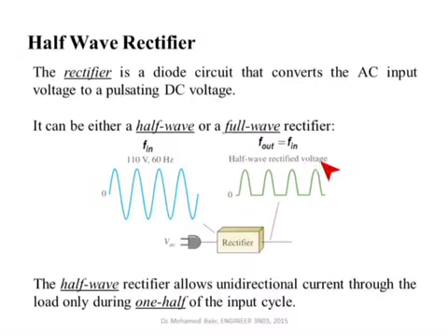So only positive voltage is allowed to go through. We call this a DC voltage because if you connect a resistor across this voltage, the current will flow only in one direction because the voltage is positive. But of course, in order to use it in powering, say, a tablet or a cell phone, you must have other circuits that will smooth this further. For example, a circuit that smooths this voltage, and then there are regulators and so on. So there are other circuits that have to be used as well in addition to the rectifier.